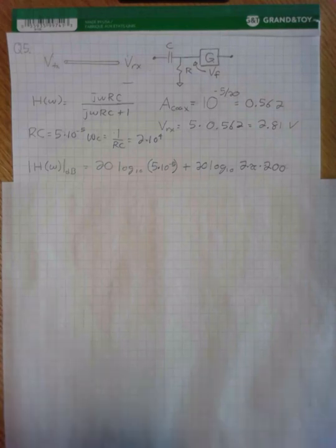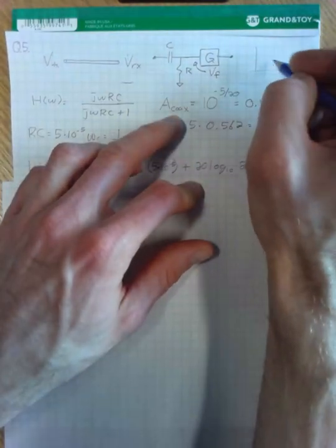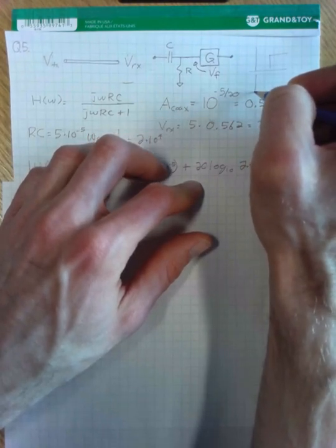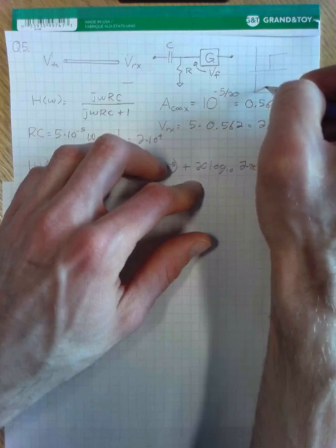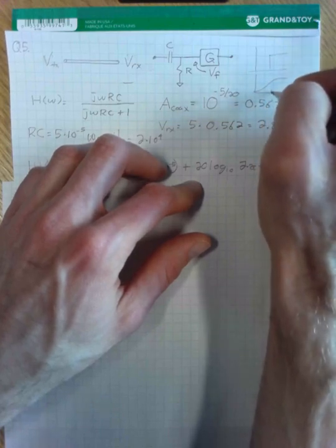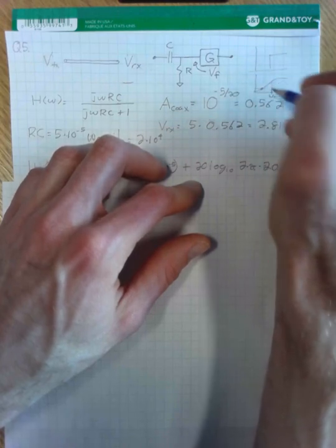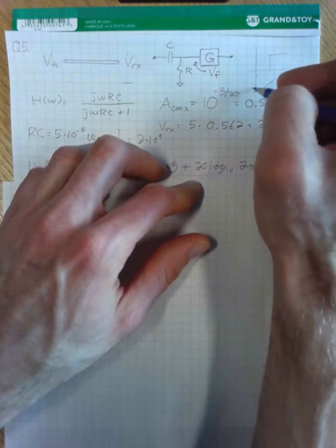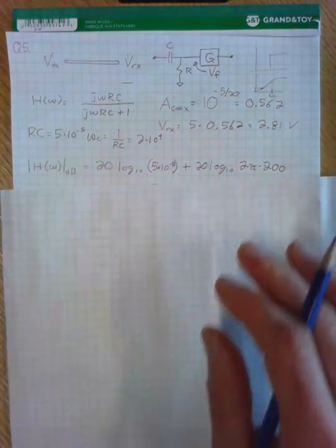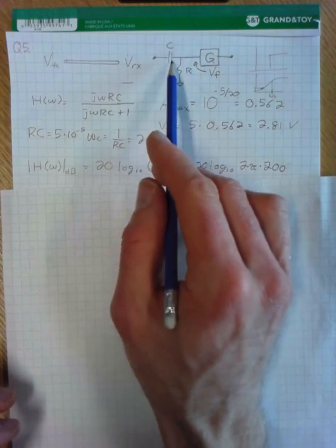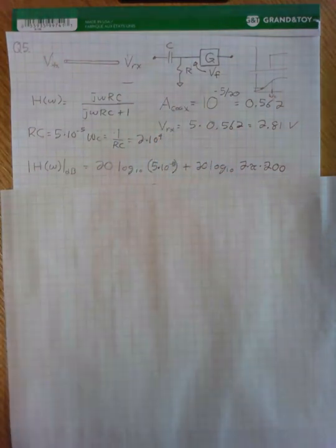So these filters, rather than having a brick wall response that looks like this, and we've seen this on the assignments and when we do our SPICE simulations, they have a response that looks like this. And so even though omega c might be right there, we're down here and there still is a gain. It does attenuate the signal, but it certainly doesn't make it 0. And so to determine the gain of this RC high-pass filter, you can try and power through the complex number math. A few people did that. A few people did that successfully.